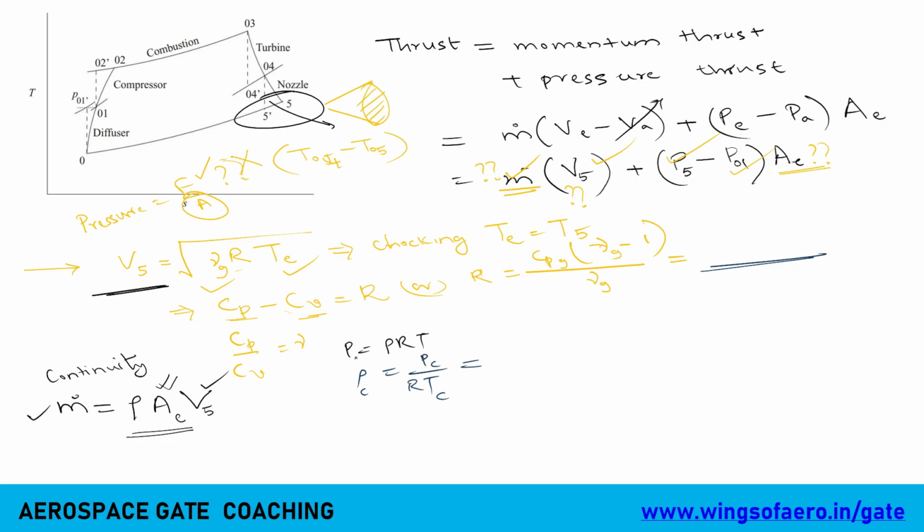They might give you the mass flow rate, or the pressure, temperature and ambient pressure, and you can use this scenario to find the thrust. Or they can precisely ask for the pressure thrust or the momentum thrust, so you should know what the pressure and momentum thrusts are.